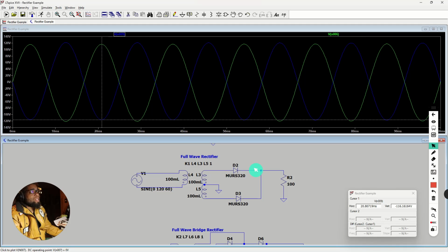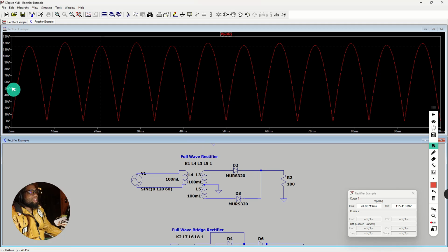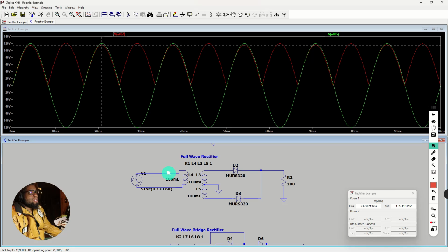And that's truly what happens until you put these diodes in there and rectify it, and then connect the diodes at one end, and then we get our full wave DC output. You see that green cycle, it's taking that and pushing it up to the positive cycle. So that green negative cycle is pushing up to the positive cycle. If we can just see that alone again, you see it like that. And again, if I look at the input, that's what that looks like right there. So it's taking that and putting it up to the positive cycle.